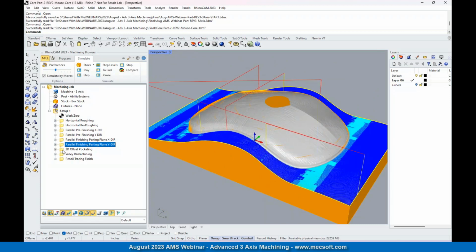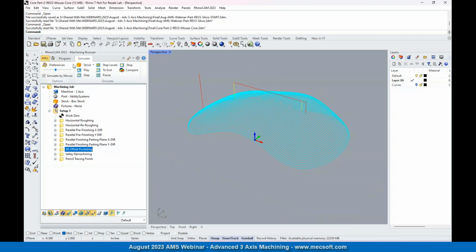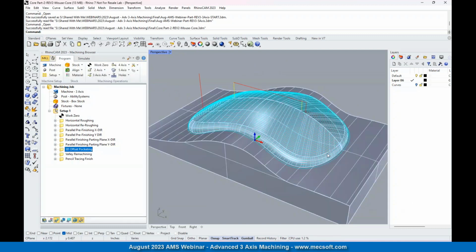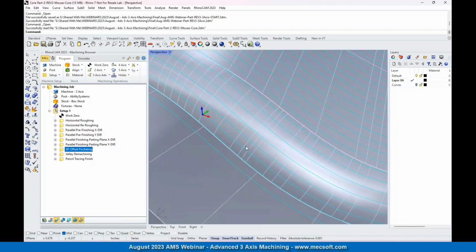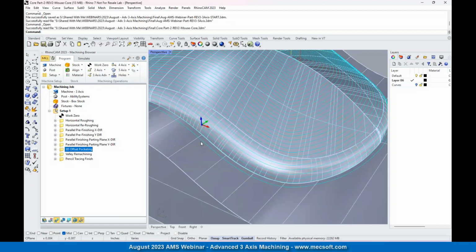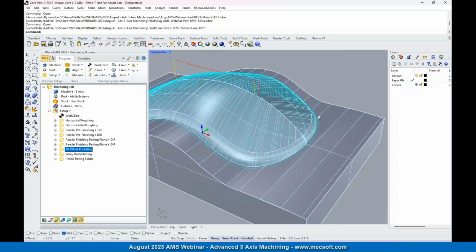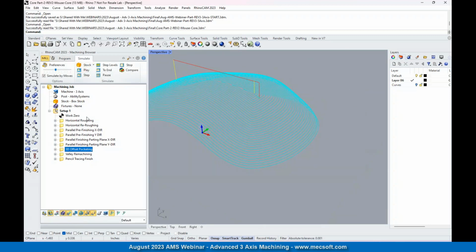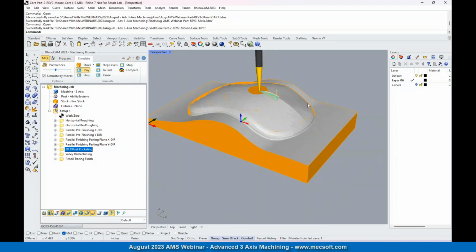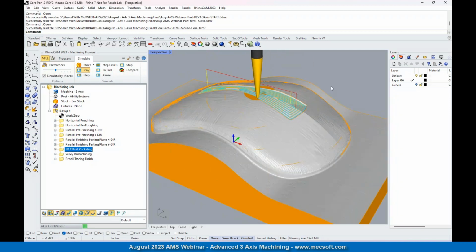Okay, so now we're going to do a 3D offset pocketing like we did on the other part. And we picked an edge that's offset from the corner. So the tool is going to go all the way down and out and all the way around that top surface. And I'll show you what that looks like. So we're just going to work its way out. I have a large step over too. So you see the cusping.